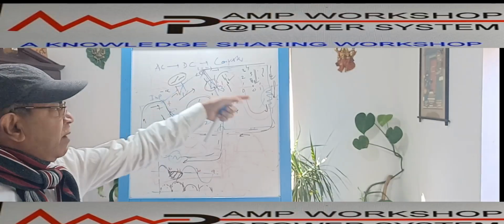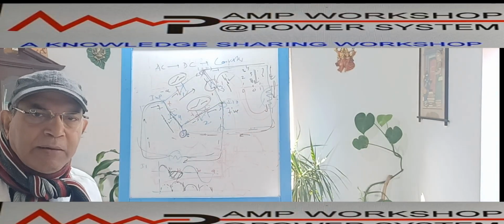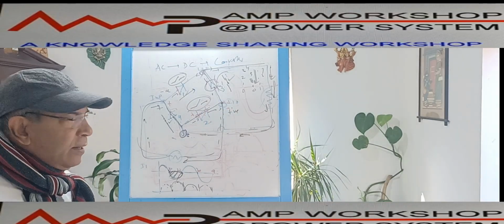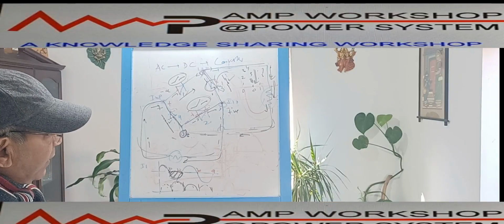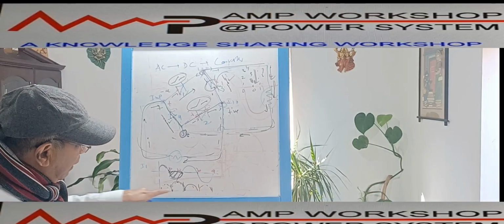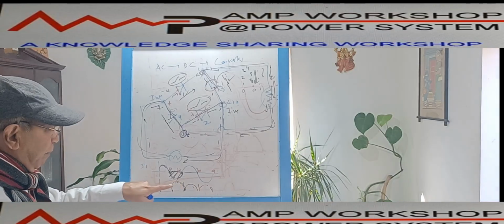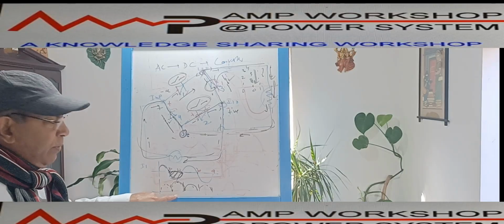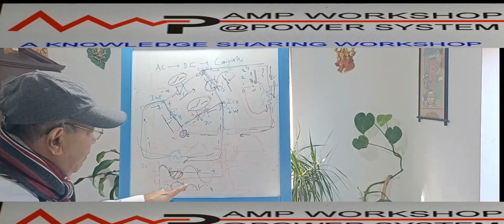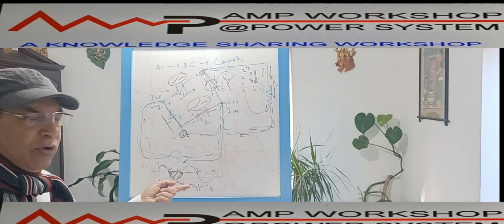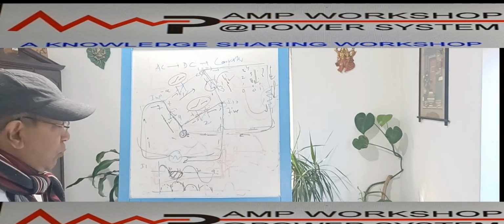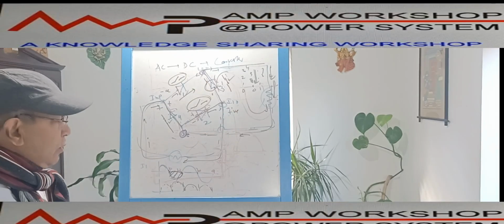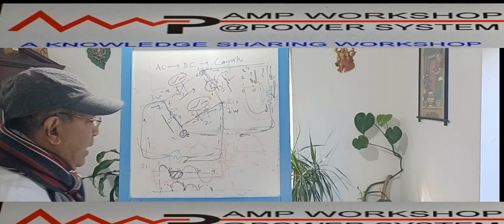That means I am getting full energy conversion. So automatically my loss of energy is recovered over here. So my efficiency will be higher. That is point number 1. Point number 2: if you do the Fourier analysis of this full wave rectifier, we will see that the ripples or the higher harmonics in the output will be very less. So my ripple content will be reduced and my efficiency is also high. So I will get this privilege with this.